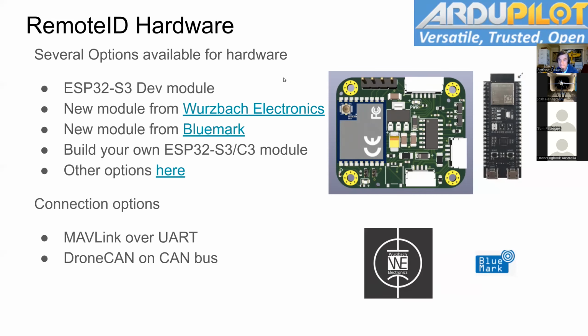Yep. Just on the CAN transceiver, it'd be good if they used an 8 megabit, even if this doesn't use that, just for future compatibility with Orange and some of the CAN stuff we're doing in the future. Yeah, ArduPilot's moving towards FD CAN support, at least 5 megabit, preferably 8 megabit. If you can do that, great. But in the compressed timeline, I can imagine a lot of the initial modules will be using 1 megabit transceivers just for availability. But if you've got a particular transceiver you recommend, Philip, please put it in the partner regulatory channel. I think that would be a very good idea for future compatibility.